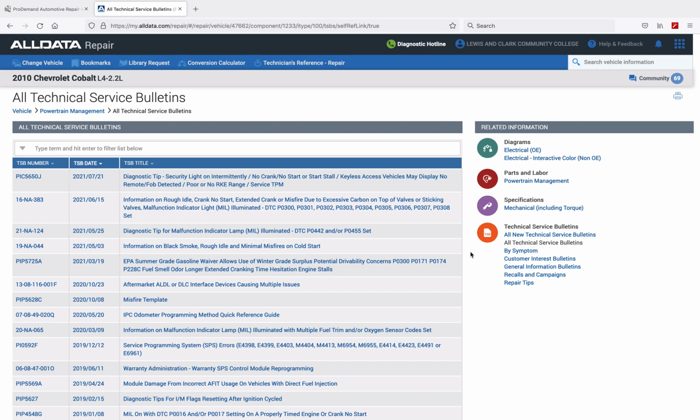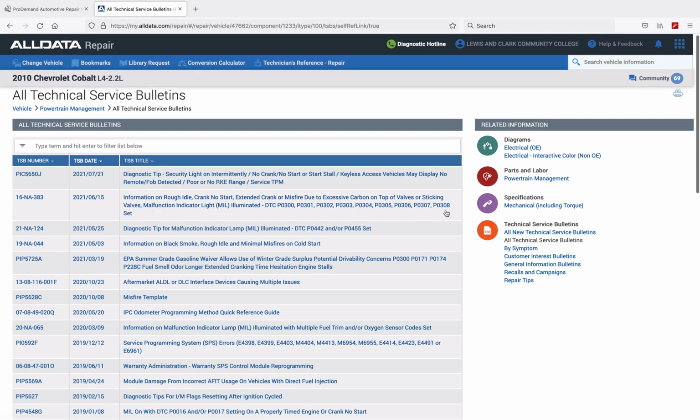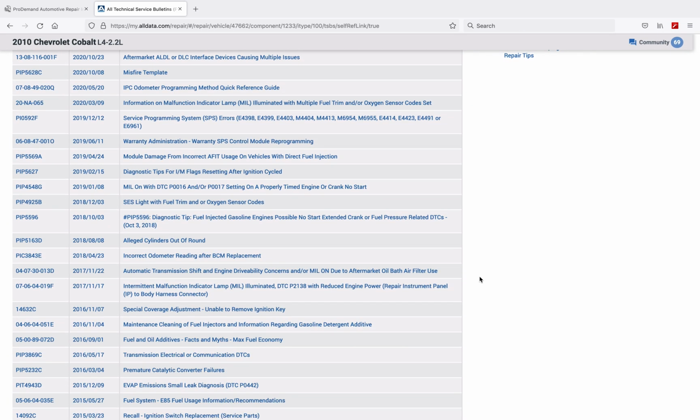Fortunately for us as technicians, if we push the issue with the OE, when we isolate this problem, a California car that landed in Southern Illinois, and we find out that it's got a fuel leak, for example, using this Cobalt, we get a hold of the OEs, oftentimes we'll find that they update the campaigns or the TSBs or the recalls to expand to broader reaching regions across the nation. That does two things. One, it allows the customer to see that we're advocating for their needs. If you're in portions of Madison County, you can't get through the test lane with an evaporative emission system leak that would be generated based on the manufacturing defect of that fuel system seal leaking.